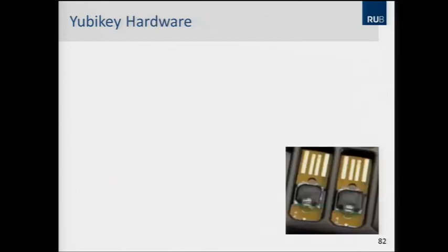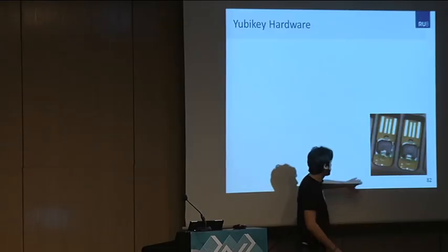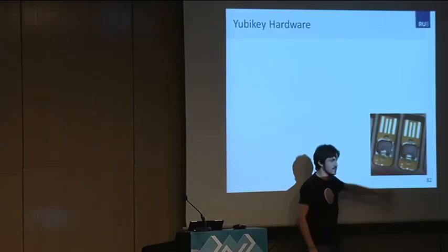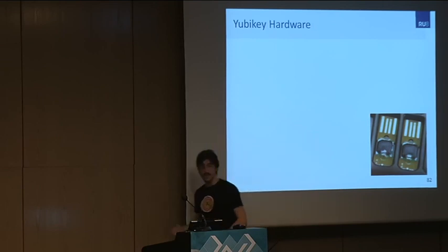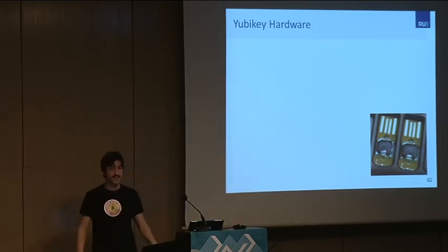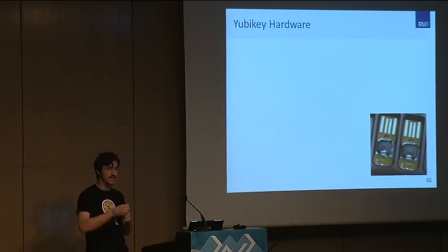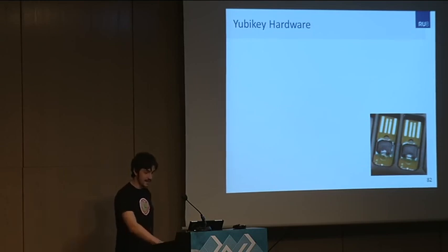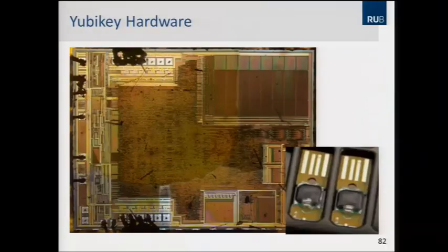Yeah, so for this we started again looking at what is inside. Is there a smart card chip inside, or is there a simple microcontroller? Here's this video. This is from an HD video that you can find on YouTube of the production. So HD videos can also leak information where the circuit is just in this molded plastic package. So we knew then where to drill the hole, put the acid, and the result is this.